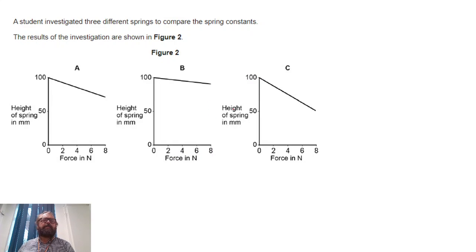Going further with this then, from your equations, you should know that the force that's required to stretch or compress a spring, so they're both the same, is equal to the spring constant multiplied by the extension or the compression. So this could be the force that's stretching a spring, or it could be the force that's squashing a spring. Okay, the equation will be the same. You need to know this equation.